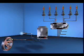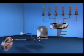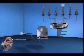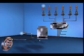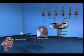We have already mentioned in this discussion how the ECM sends 6 spark timing signals and a spark reference signal for each cycle of the firing order. The ECM commands the ICM to enter the multiple spark discharge mode by the length of the spark reference signal. The signal for multiple spark discharge is approximately 4 times the duration of a spark reference signal for single spark discharge.